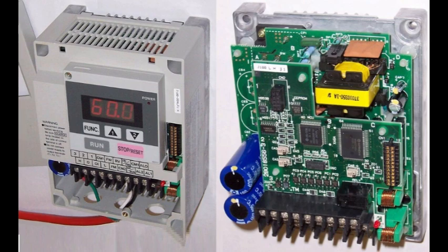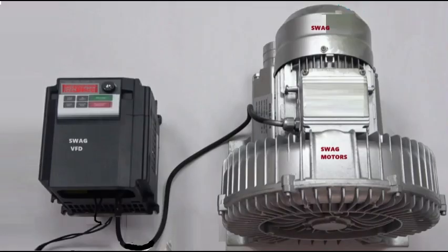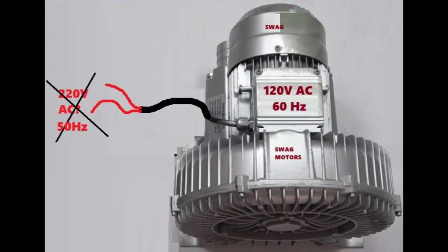Motors and similar devices don't really work well when they have to run at frequencies that aren't what they were designed for. If they do, they can become really inefficient and might even get damaged over time. For instance, a motor that is meant to run at 60 Hz shouldn't be used at 50 Hz or other frequencies. If you do that, it can lead to problems like the motor overheating, running too fast or too slow, and using way more energy than it should. This can make everything less efficient and shorten the life of the motor.